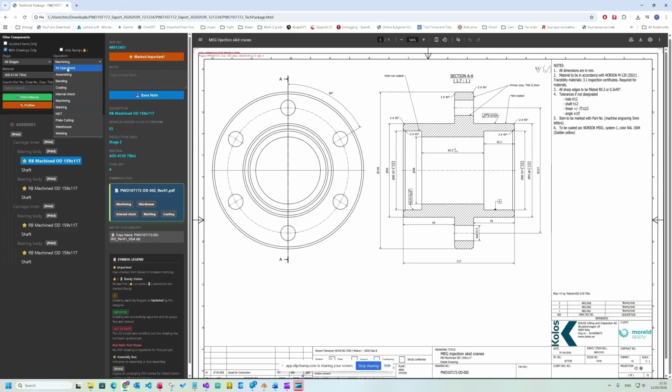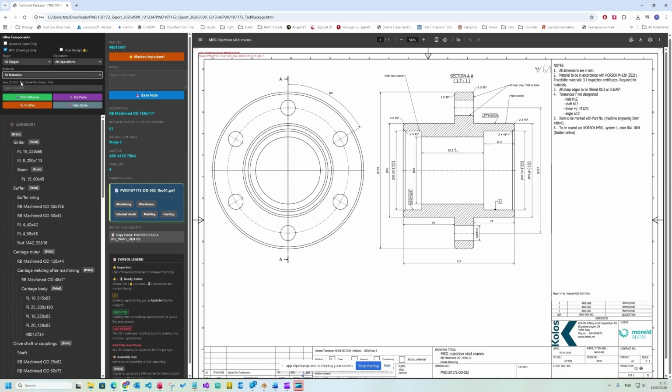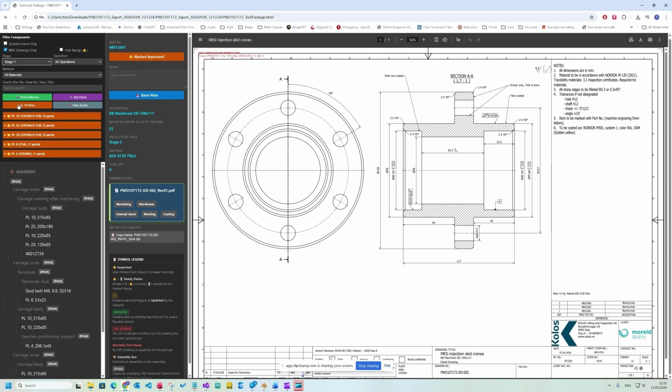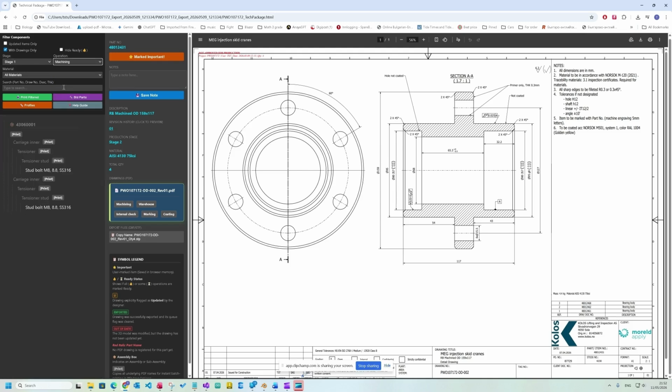The logic of production stages. To keep the shop floor moving efficiently and prevent bottlenecks, the file manager organizes the workflow into distinct production stages. The logic here is strict. Stage 1 items must be completed first because they supply the subsequent stages. For example, an assembly in Stage 2 cannot be welded if the plates haven't been cut in Stage 1. This same rule applies to Stage 1 machined parts. Note that raw material profiles do not have assigned stages and should be cut independently of this sequence.